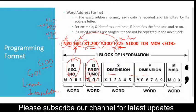Feed rate can be in two senses. One is mm per minute and the other is mm per revolution. Let us say feed rate, if I write 0.15 to 0.4 mm per revolution, or I could write 200 to 400 mm per minute. Okay, I can give feed rate in two senses.